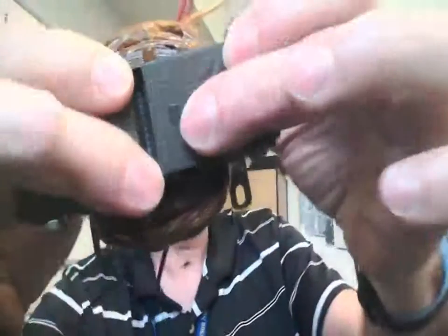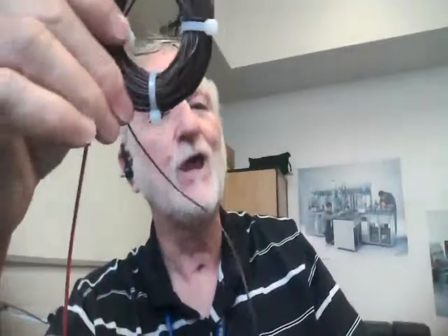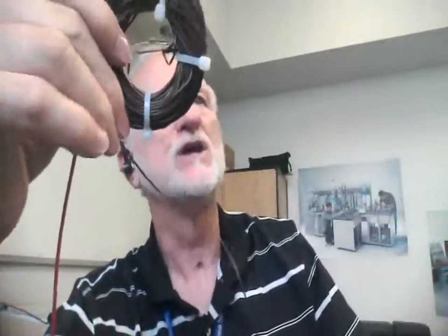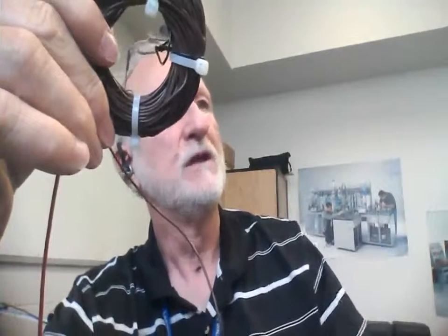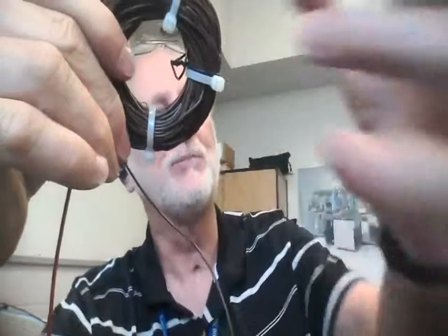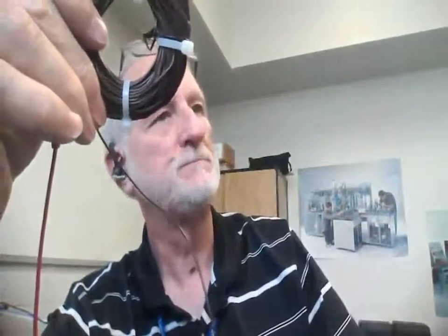So we have this core right here. If I took the core out, I'd still get coupling, but my output voltage would drop right down, and the resistance of the transformer would go way, way up. That's why I couldn't run a light bulb on this thing. That's why I'm running a light emitting diode, because I have a very poor coefficient of coupling. Y'all understand that? So if I change the coefficient of coupling, then I can change the output of the transformer.